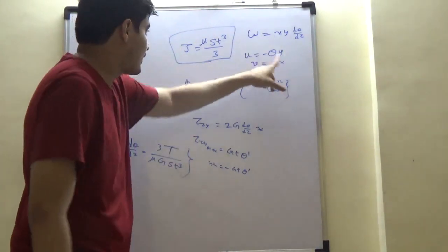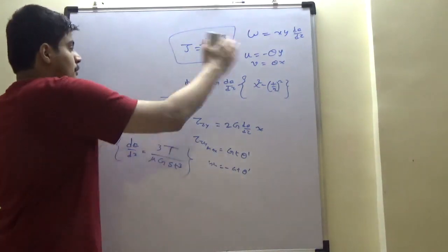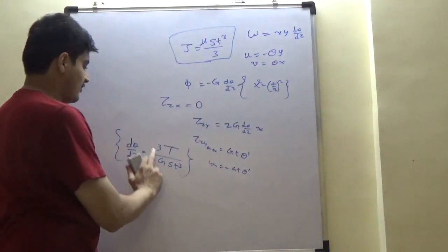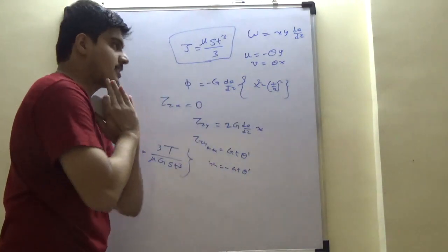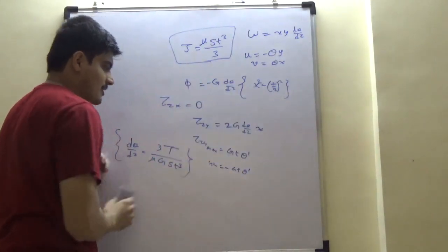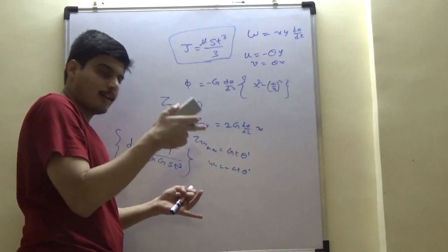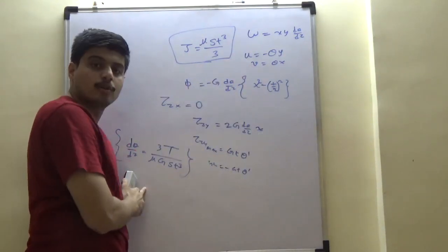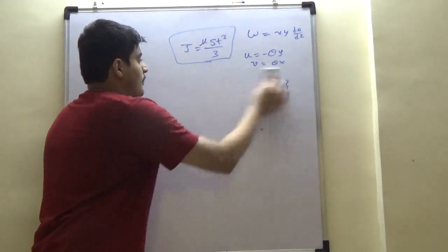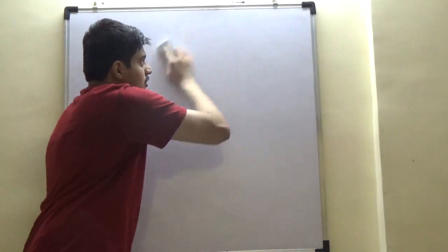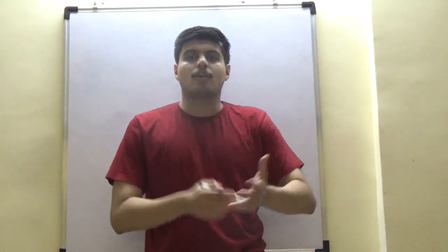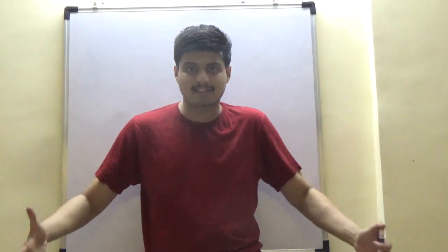Thin sheets, therefore, we said that for S by T, Prandtl gave us this beautiful analogy and outcomes, and he gave the correction factors. So the entire problem is very easily solvable, and thin sheets are particularly important in our aerospace analysis, because of which this Saint-Venant's warping function and membrane come together to give me this solution. This ends our entire theoretical analysis and basis physics and mathematical foundations of torsion as a chapter. We are closing chapter 2 from a theoretical, mathematical and physics point of view.